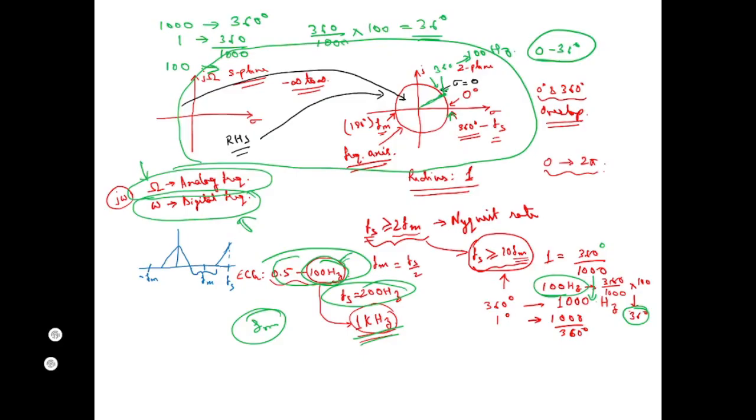Right? So, is there any way around that? Yes, there is. After you have sampled the data, you have 1000 data points per second. What is the minimum requirement per second for the data to be reconstructed faithfully? 100 hertz is your maximum frequency, right?